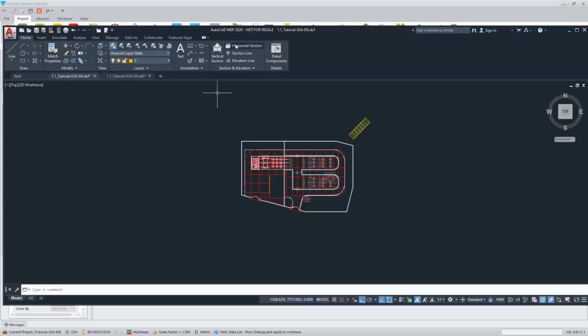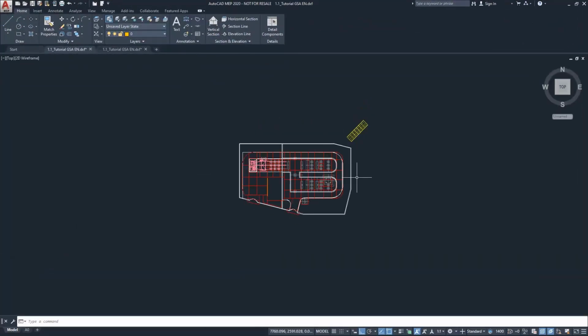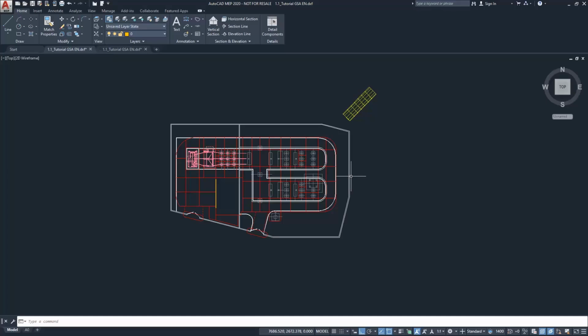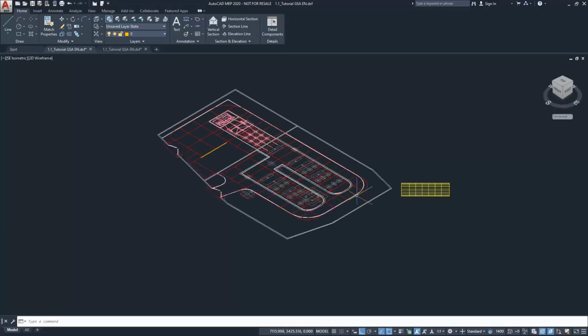In the help desk, you can download this XGSlab template. Here is a tutorial GSA EN DXF, and the red conductor represents a grounding system that we'd like to evaluate. This is a typical substation, and with that, the grounding system is drawn two-dimensionally with the intention of being able to be printed. And we'll have to correct for this in our importation by shifting this grounding system into the soil in our model.